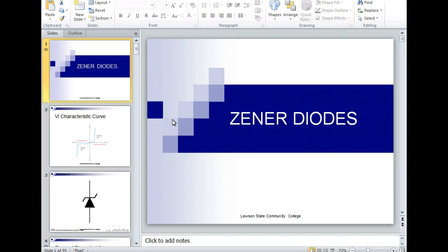It says its purpose is to act as a voltage regulator either by itself or in conjunction with other semiconductor devices. So if I looked inside a 7805 at the actual schematic, it's going to have Zeners in there. Any of these voltage regulators are going to have Zeners in there. So we use a Zener as the reference, and then we have other solid-state devices to actually get the big currents and all that other kind of stuff. Or we can use Zeners by themselves.